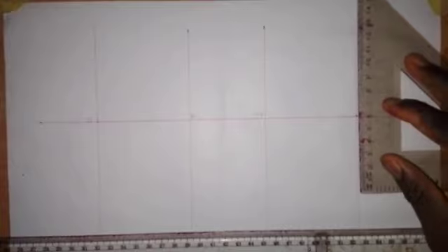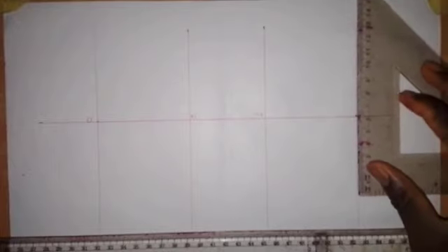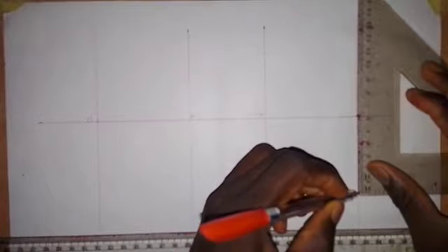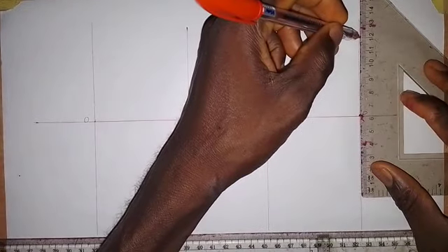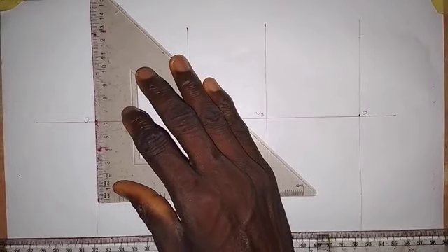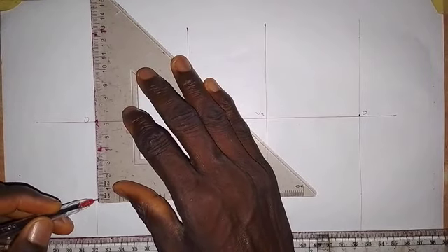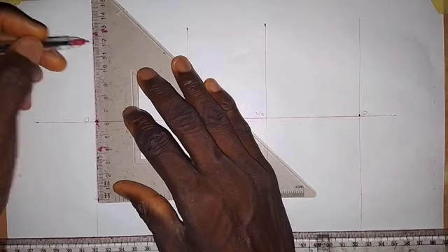The next thing I'm going to do is take the distance of the point. This is the axis of symmetry. The point that we are given is 60 millimeters from this axis of symmetry, so it will be down here or up here. I'm going to take 60 millimeters from this point O down. Then I will take 60 millimeters up like this. Also on this side, I will take 60 millimeters down. Since we are constructing two branches, I need to replicate the same thing on this side, so I also take 60 millimeters up here.